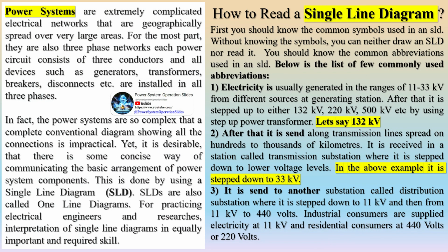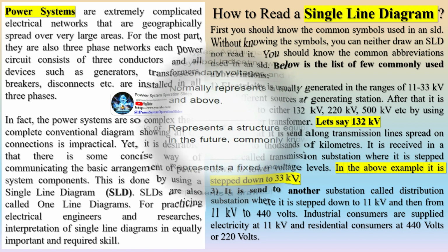The one-line diagram has its largest application in power flow studies. Electrical elements such as circuit breakers, transformers, capacitors, busbars, and conductors are shown by standardized schematic symbols. Instead of representing each of three phases with a separate line or terminal, only one conductor is represented.